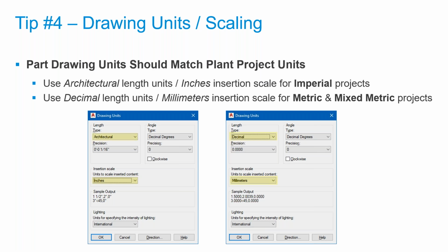And this is important because, unlike regular Plant 3D Python-based geometry, block-based geometry is specific to the units that it was created with. So even though I could take an ASME catalog and use it in an imperial project or a metric project, if it doesn't have block-based geometry, if it's just Python scripts, I can do that. But if I've got block-based geometry, it's basically units sensitive.